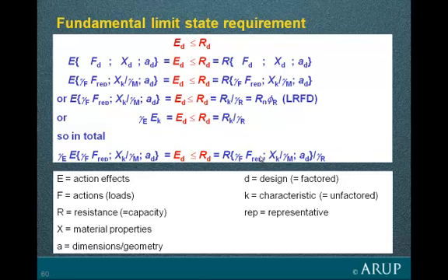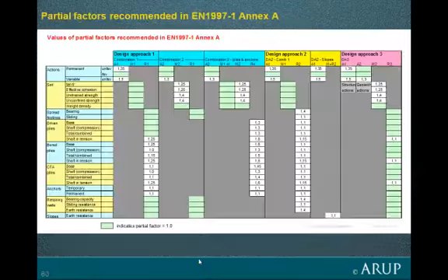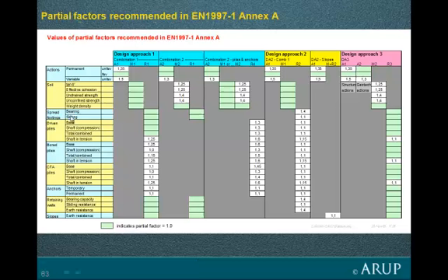And you can see that there are various alternatives here. Various Oasys programs can be used for these calculations, and the alternatives have led to 3 different so-called design approaches being available in Eurocode 7. The design approach is a national choice. Very briefly, design approach 1 requires you to do 2 different calculations, to check every ultimate limit state by 2 separate calculations. In the first calculation, the loads are factored, but the material strengths aren't. In the second calculation, the loads are barely factored, just a small factor on variable loads, and we factor material strength instead. Slightly different approach is taken to piles and ground anchors.